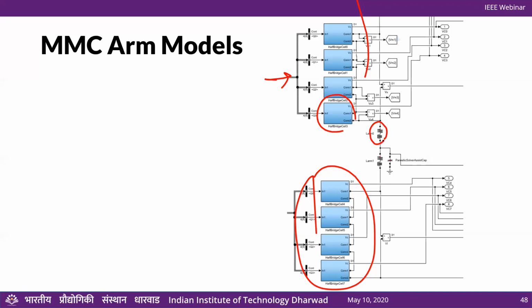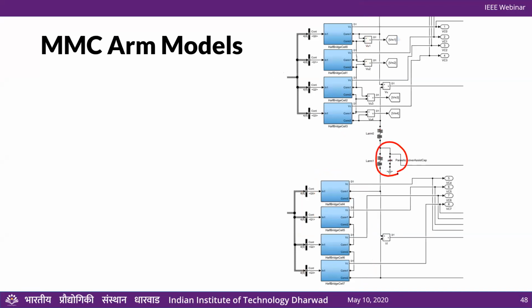And the other thing is that because these are two inductors driving this node here, I find that it helps simulation much of the time just to add a small solver assistance capacitor here. So I just make this node a voltage node by adding a small capacitor. This is in picofarads, but just it being there helps the solver get things right.